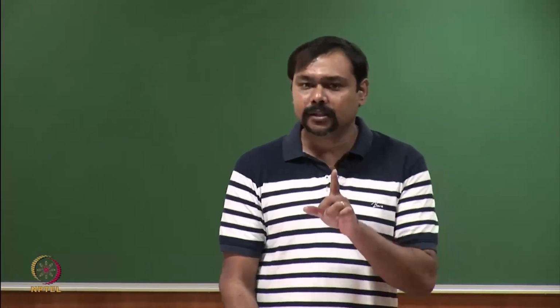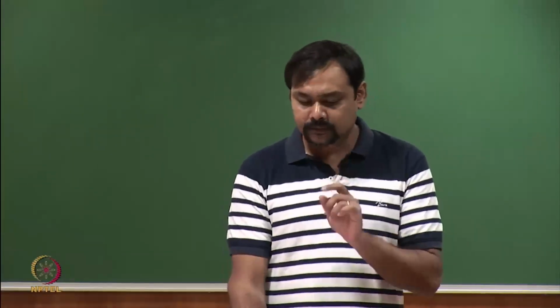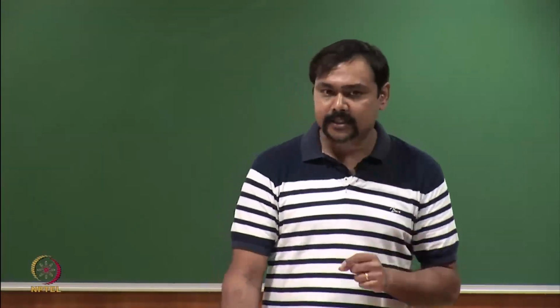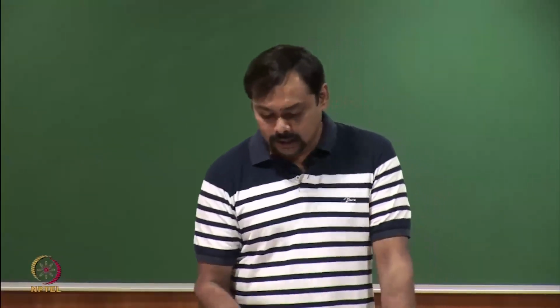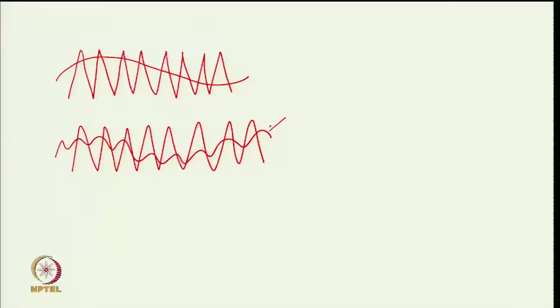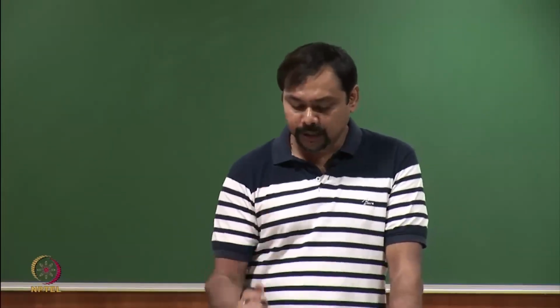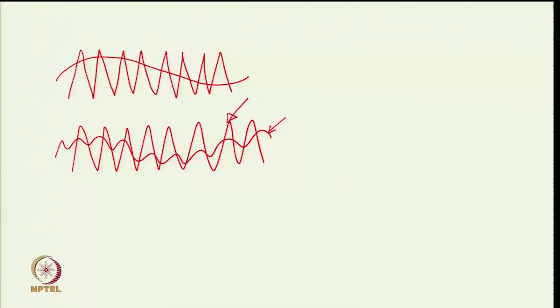The only condition that we have to preserve is that the highest frequency component in this non-sinusoidal waveform which we are generating must be very low compared to the frequency of the triangular waveform.